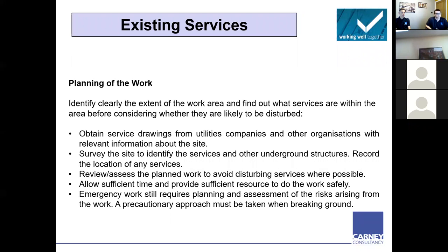Assess the planned works, making sure, can you avoid disturbing them? Because again, can you reroute something? Can you avoid disturbing them? Sometimes you can, sometimes you can't. But you need to make sure there's sufficient time and sufficient resources to carry out the works safely. Sometimes this might be emergency work, but again, we need to assess the risks arising from the work, making sure we're taking a precautionary approach when we're breaking ground or breaking into walls where there could be services present.